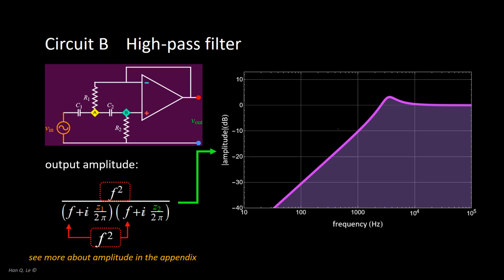This is a log-log plot of the magnitude of the amplitude as a function of frequency, known as a Bode plot. It goes to 0 as frequency goes to 0, which means that unless a signal oscillates, it has 0 output. On the other hand, if the frequency is above approximately 3 kHz, the output magnitude is constant and equal to the input. This behavior, which involves the blocking and attenuation of signals with low frequencies, but allowing high-frequency signal passing through, is called high-pass filter.